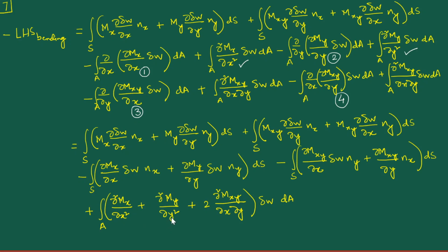And please note that in light of what I had mentioned earlier, these terms are eventually what are going to lead to, or contribute to, our governing differential equation. And because they have now been expressed in terms of this bending rigidity and this operator on W, you see that it is actually shaping up to a nice form. The final governing equation that we are going to end up with will have a certain symmetry and niceness to it.